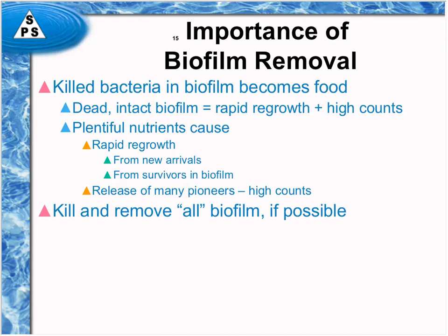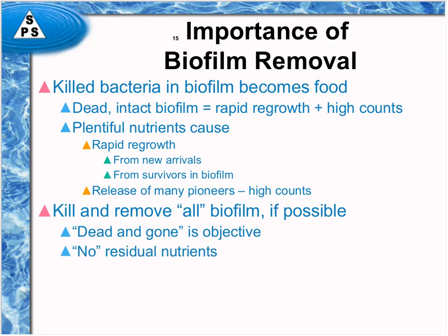So the objective is to kill and remove all the biofilm if possible. Dead and gone is what you're shooting for. You want no residual nutrients left in the system if you can keep from it. What happens when the sanitant starts to dissolve and degrade the biofilm is it converts it from that insoluble matter of biofilm into soluble total organic carbon, or TOC.